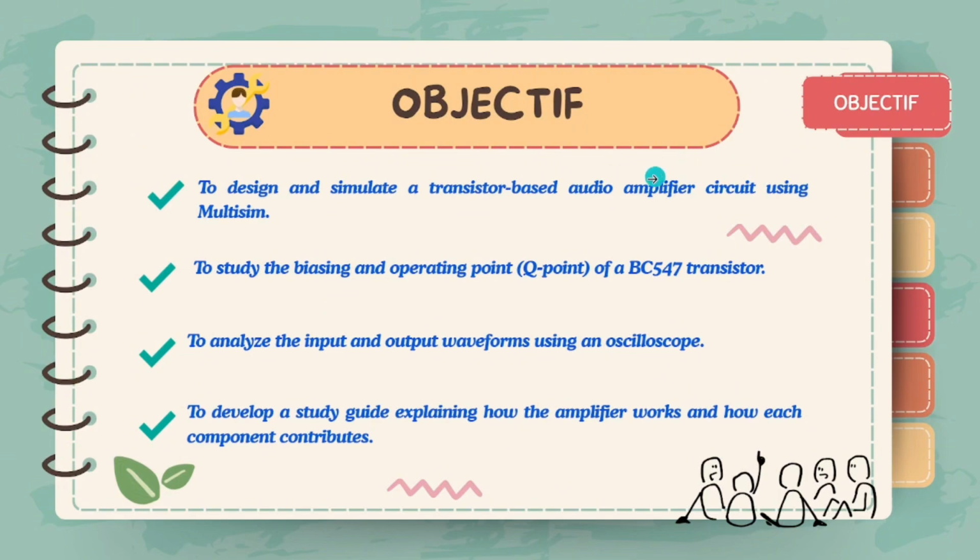In this step you can see we use the Multisim software to design the schematic before building it in real life. Later I will explain the circuits we used, and the simulation allows us to check if the circuit amplifies correctly before implementing the hardware version.